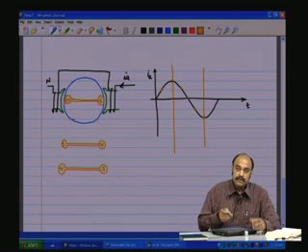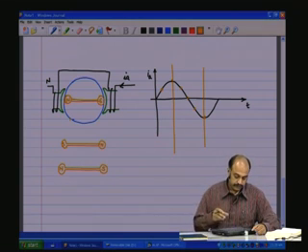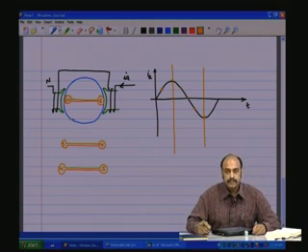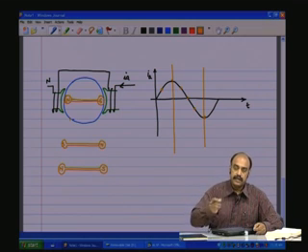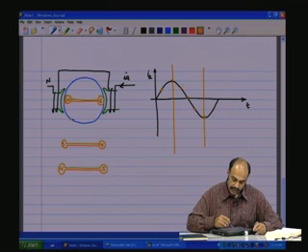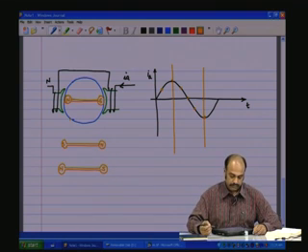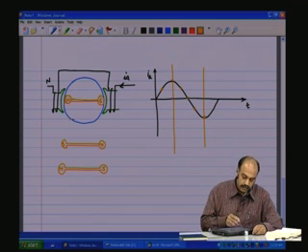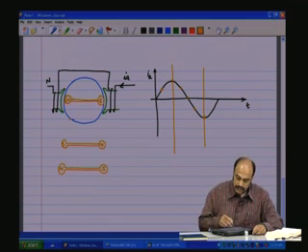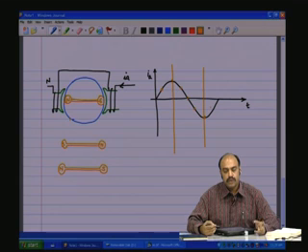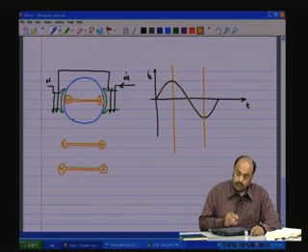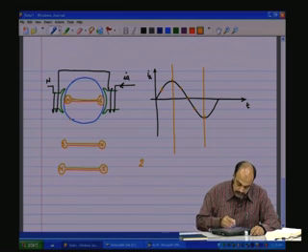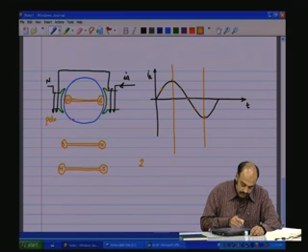So inside, if we take the imaginary dumbbell on the rotor rotating, it means that the flux MMF inside has rotated 180 degrees for a half cycle traversal of IA, and it would have rotated a full 360 degrees for a complete full cycle traversal, or 2 half cycle traversal, of IA. That is for a 2-pole system. That is, this is pole 1, pole 2.